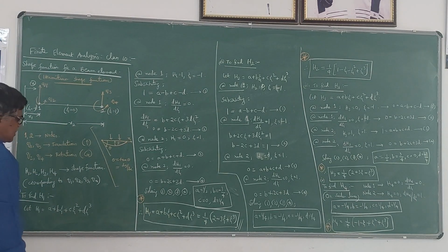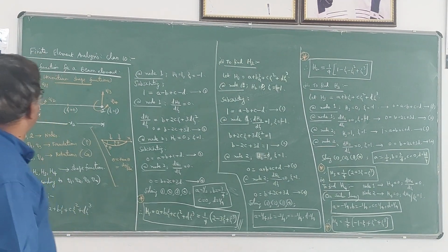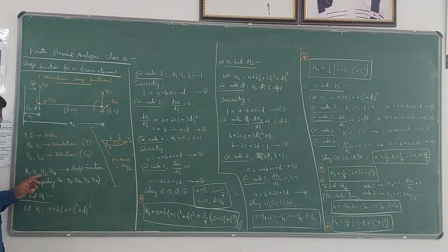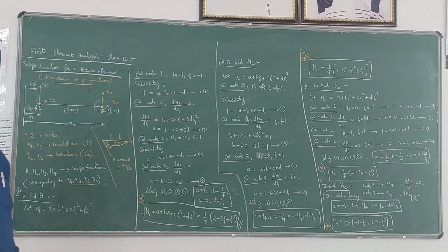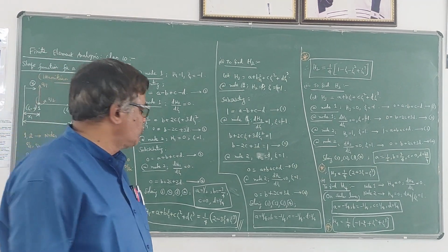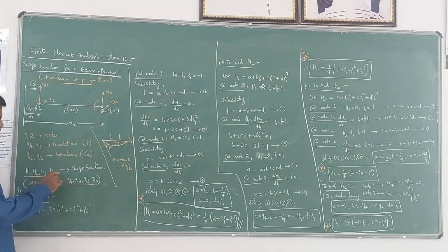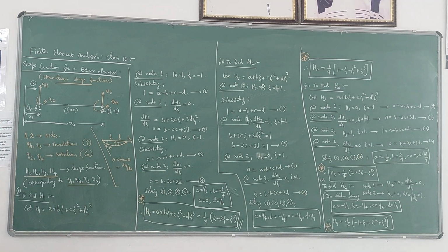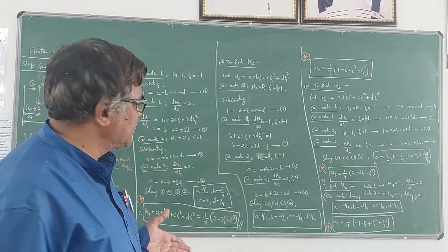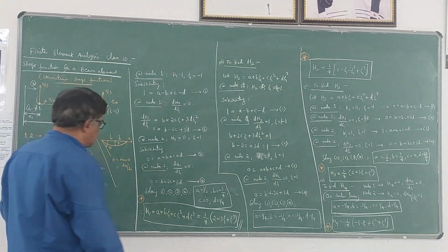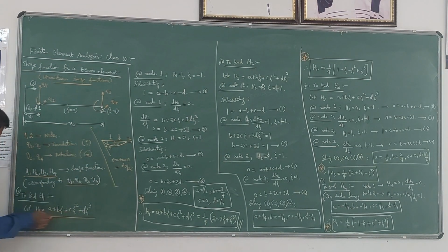Now the shape functions, since they are also called Hermitian shape functions, I will call them h1, h2, h3, h4. These shape functions correspond to these 4 nodal displacements. Here Q1, Q2, Q3, Q4 are called the nodal displacements. So these shape functions correspond to these nodal displacements. Now we have to find one by one all the 4 Hermitian shape functions, one for each nodal displacement, by assuming the shape function in this form.